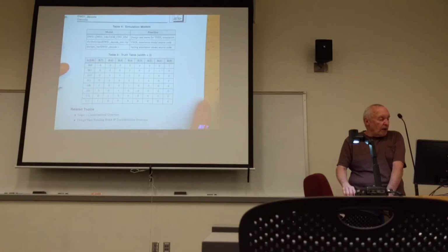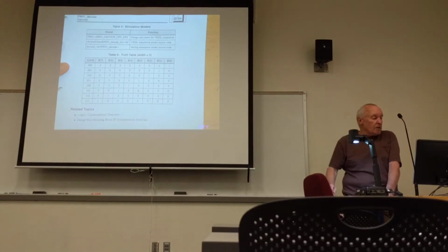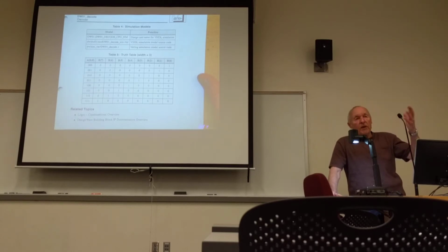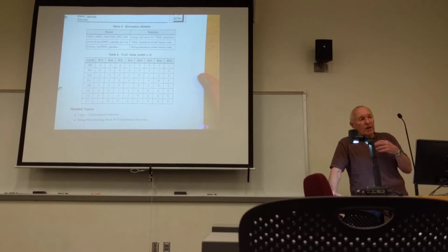So they give you both VHDL and Verilog simulation code. The simulation code is different from the Verilog source files. The simulation code is just a Verilog or VHDL module, but it doesn't have all of the particulars of how it was actually implemented with case statements or continuous assignment statements or whatever. It's just a simple module that can be used for simulation purposes only.